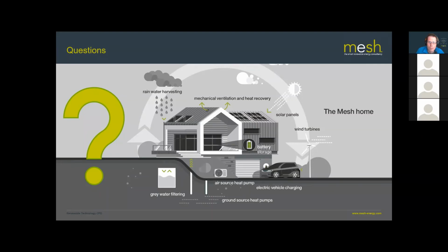So let's start with a question from Jane. Jane Clayton, thank you for your question. Is access required for annual maintenance? I think I've answered that. Yes, it is, ideally, because you need to be able to inspect the panels, clean them, and also do things like inspect the wiring and check isolators. Although obviously isolators should be in an accessible position.